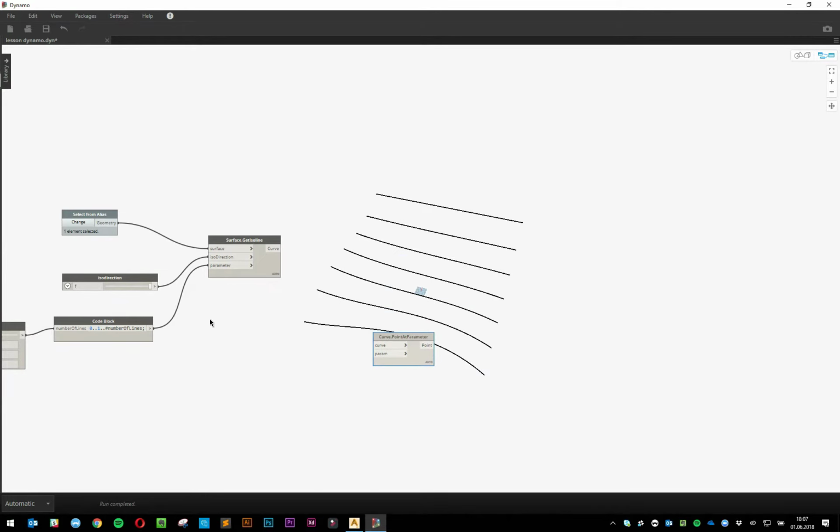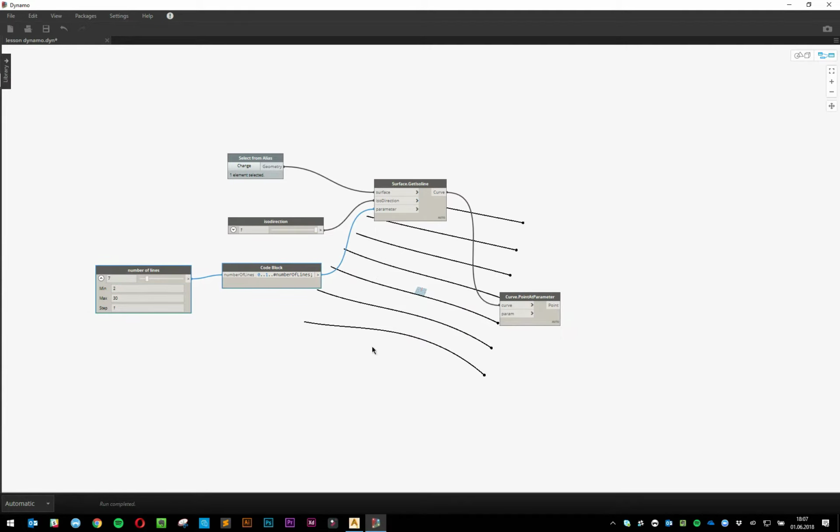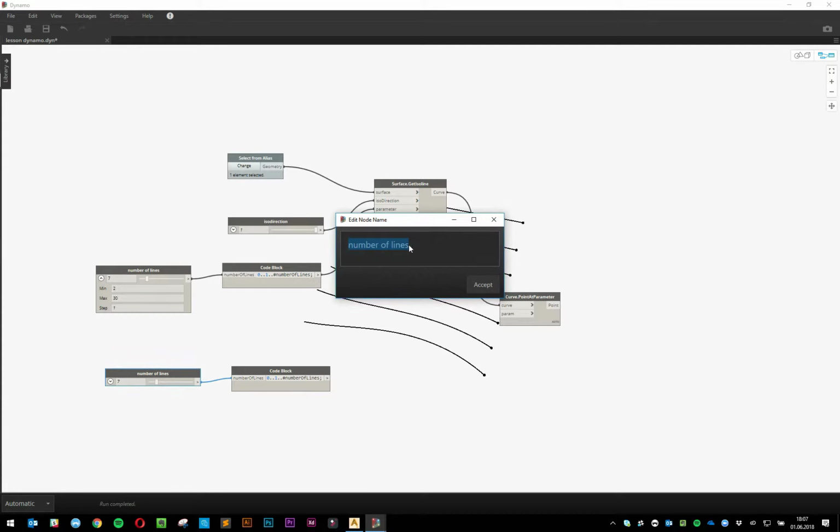It works the same way as the isoline: take the curve, put that in, and it's already put the default value 0, so you can see it's got 1 point for each one. Anyhow, we want to do the same logic as here, but we want to use 2 different new nodes. Cool. Let's duplicate those. Number of, let's call it triangles per line.